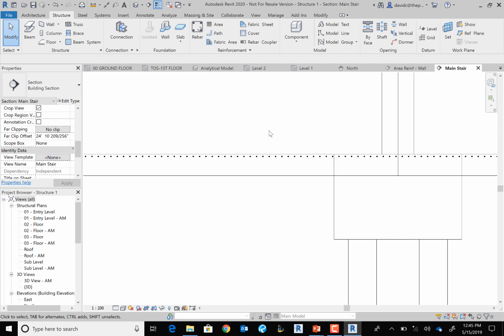Yeah, I mean, that one's hard, just because when you're working outside of Revit, your design becomes disconnected. So you have to keep constant track of what's changed so you can update it. I mean, Link IFC is nice, which I think should be able to link those in, right? Those are the new 3D types of models. You should be able to link those in with that IFC.